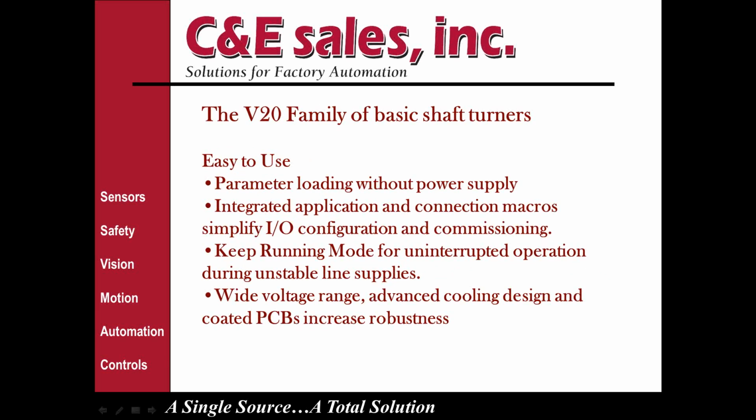One nice feature of the drive is that by using an optional parameter loader, you can move the configuration from one drive to another. You can record it on one, set it up and configure it without the 480, or excuse me, the line voltage to it, and then you can move that to another drive to duplicate it.